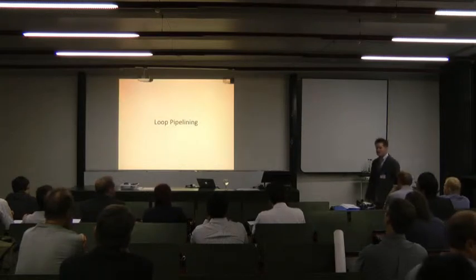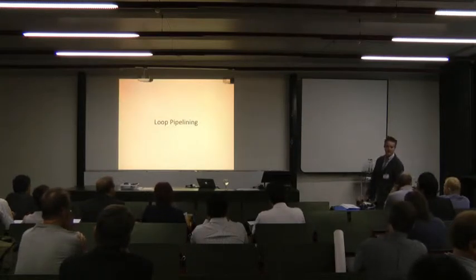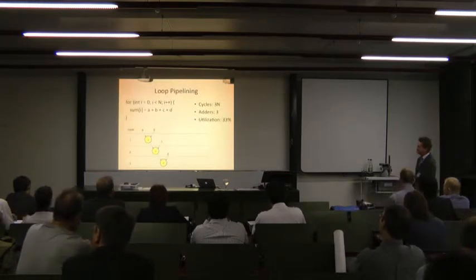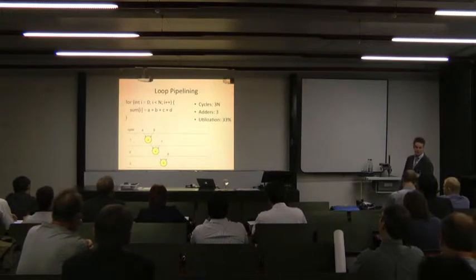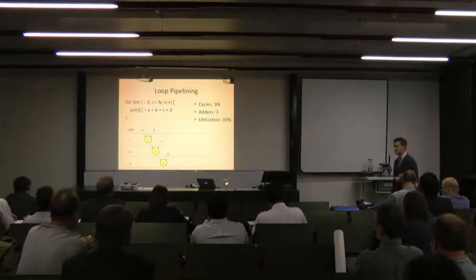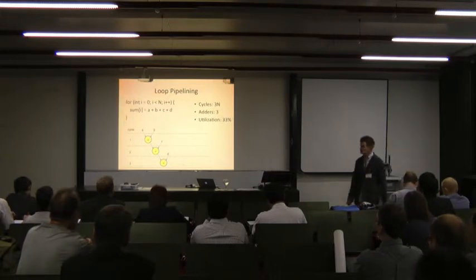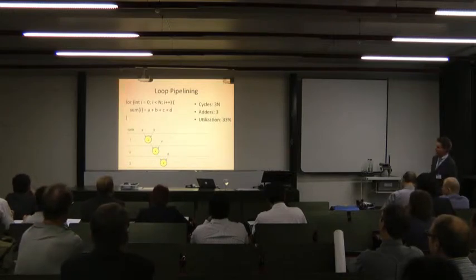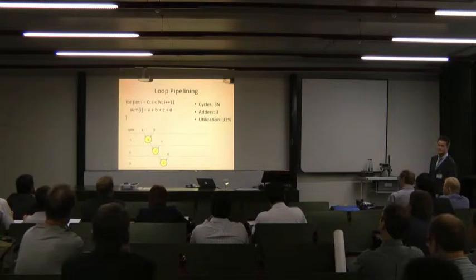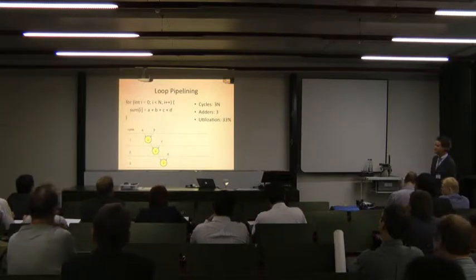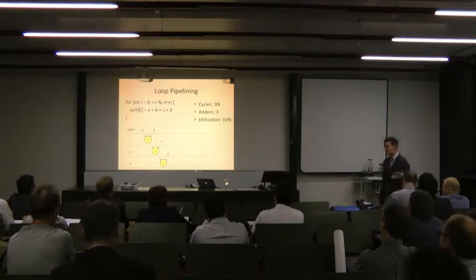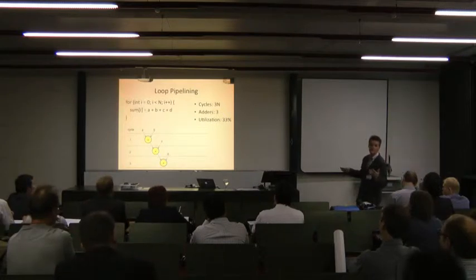Now, an important thing you want to do in high-level synthesis in scheduling is something called loop pipelining. In loop pipelining, this is really a key concept in high-level synthesis. In loop pipelining, we're going to overlap loop iterations to produce a much, much faster circuit. And this is actually crucial for high-level synthesis to get good speed. So here's an example of a loop which does 3 additions. One way to schedule that loop is you could do 1 addition in each clock cycle. And if we had n iterations of this loop, it would actually take 3n clock cycles to get all the work done. Make sense? And we would only be using 1 adder in each of the clock cycles. So our utilization of adders is kind of 1/3 in terms of their busyness, right?